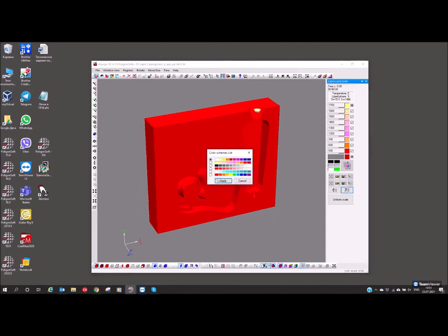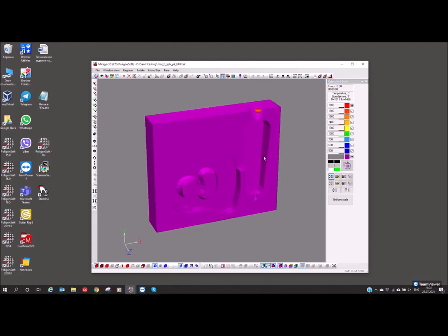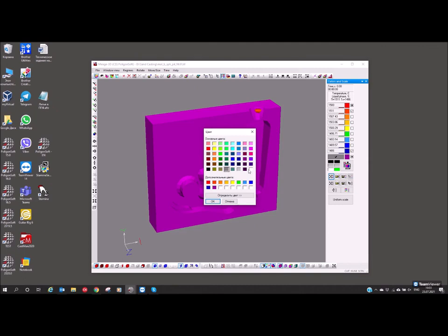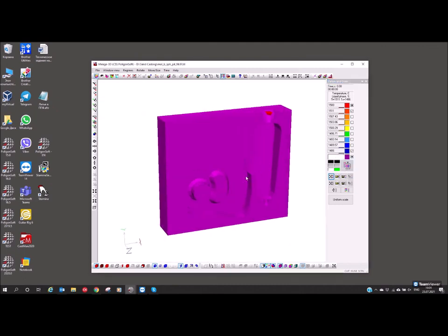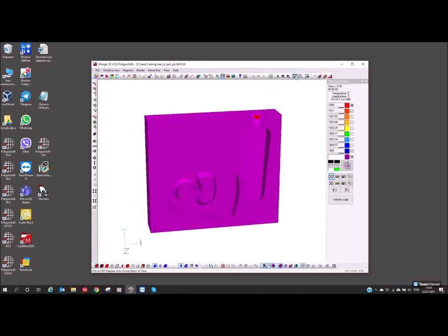And here I can set another color scale, and I know the initial temperature, it is 1580, and I see the liquidus temperature, I can put it here, and for example the solidus temperature, and apply all the settings with a white background, so I can look at the temperature field to see how the temperature of the liquid metal changes.